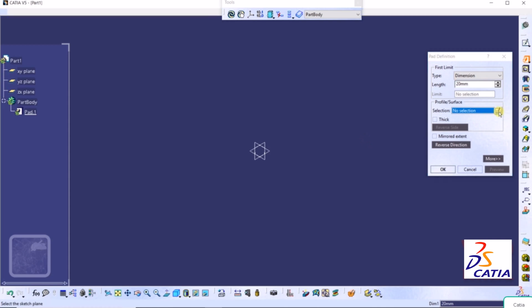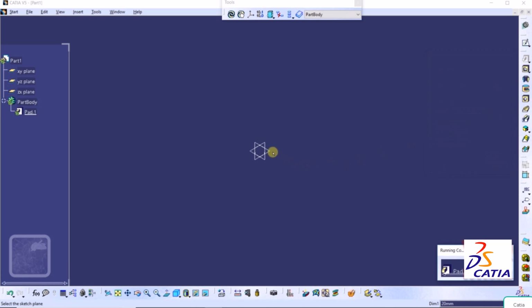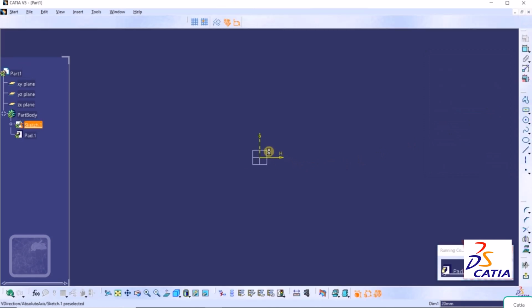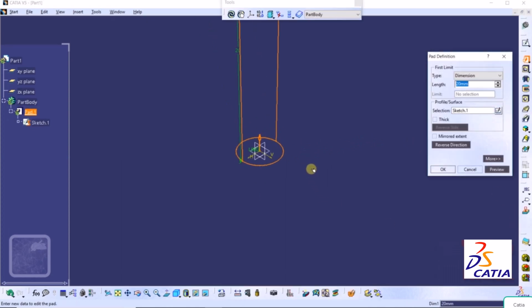Click on this create sketch. I select this XY plane. So onto this plane, I draw a circle. Go to the circle tool and draw a circle like this. Click on this exit workbench and then insert this value 5 and click on preview. So in this we can see we have limit 1 option. So this limit 1 is basically an arrow to drag the height.